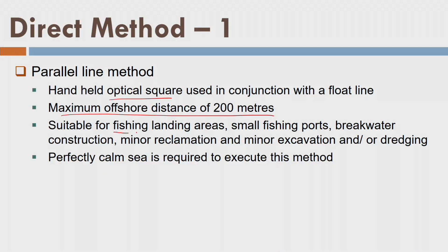And secondly, the assumptions of low water current and no wind velocity are appropriate there, right? That is why this method is restricted to 200 meters from the shoreline, or from some jetty and so on. So it is only suitable for fishing landing areas, small fishing ports, some breakwater construction, minor reclamation, minor excavation or small dredging purposes, right? And a perfectly calm sea is required. I think I have repeated all the things again for you.